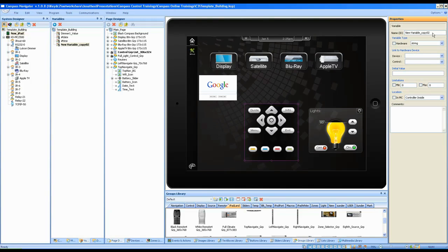And finally, the third variable that is not in fact a string is going to be hash battery, and that will be an integer type variable with limitations of say 0 through 99. We'll go ahead and apply those limitations. And actually, because this links to the iPad, the initial value is not important. We don't need to enter any initial value here.